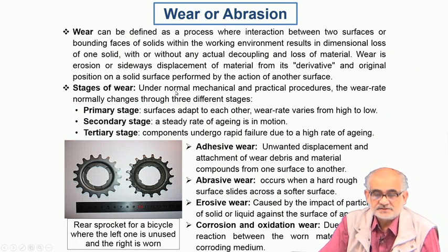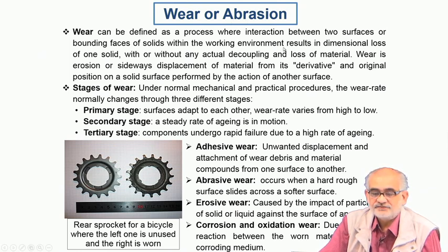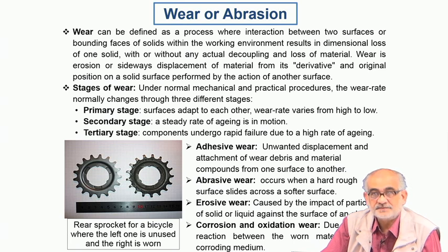Another very commonplace mode of deformation and degradation under mechanical activation is wear or abrasion. So here again we are talking about relative motion between two surfaces, and when we have such relative motion, then we expect that there will be a certain amount of resistance to sliding motion, and that's primarily because all solid surfaces which are synthetically produced or manufactured by some artificial means will definitely carry a certain amount of asperities or roughnesses.